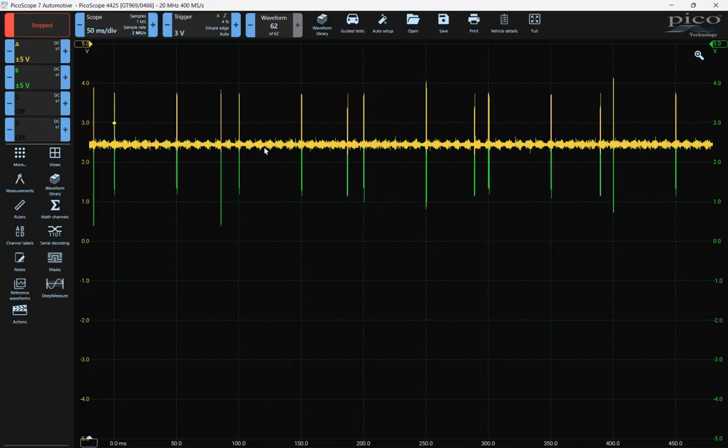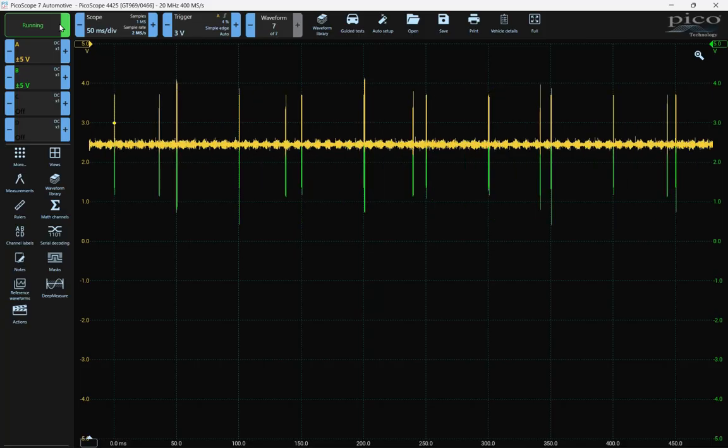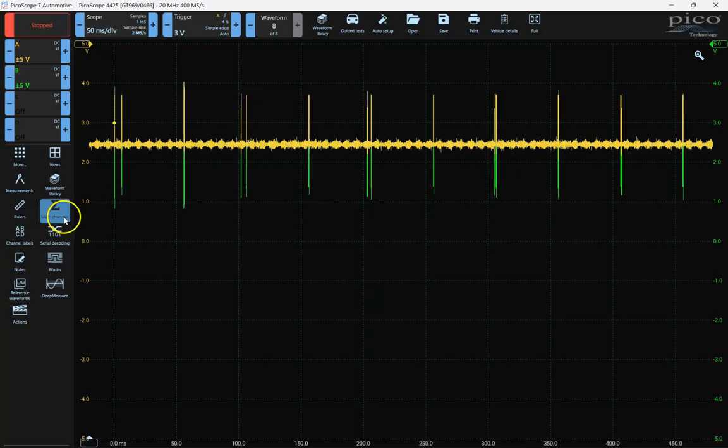So I have a NOx sensor, I have a couple of other sensors, and the Vector CAN case. Those are my small CAN network. I've got probably 10 or 15 foot of wire harness here. It's passively terminated, but it's a little more noise than you would see on a real vehicle, but it really isn't that much of a problem. I'll go ahead and pause it. We'll go ahead and prove that.